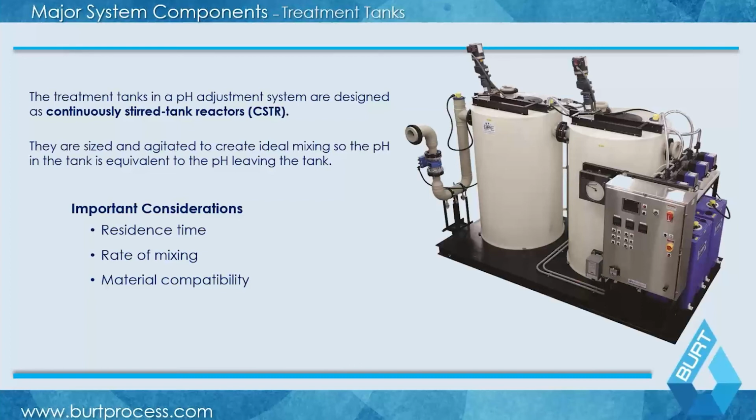And you accomplish this through three primary things. Residence time being most important. And residence time for a pH neutralization tank tends to be somewhere between 15 to 30 minutes, again, depending upon the nature of the waste, and then the rate of mixing that's going on in your system.